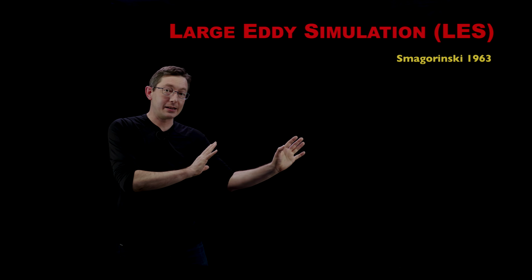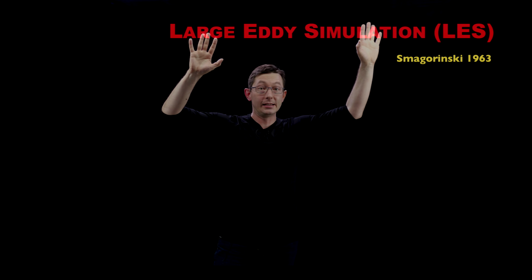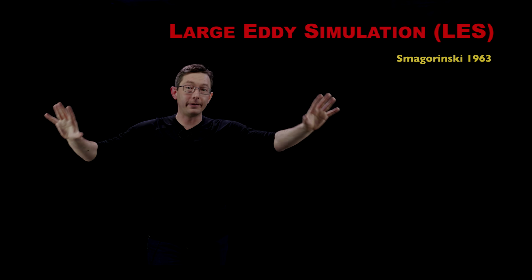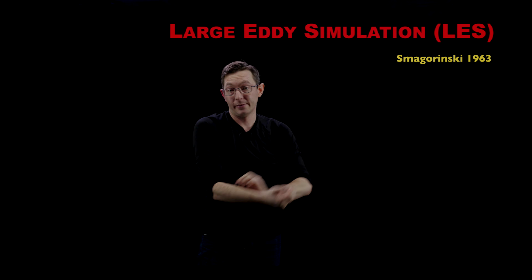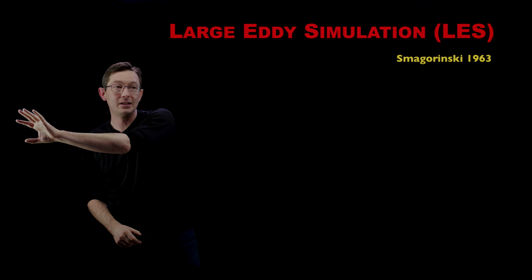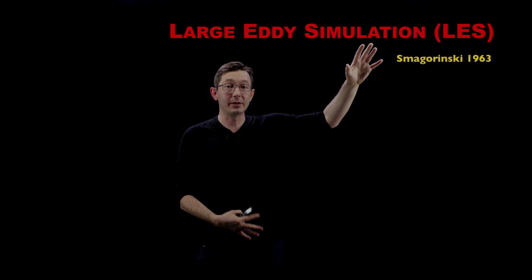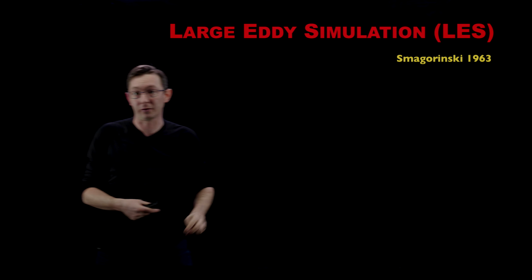Now for the rest of this, I'm going to tell you about a whole different perspective called large eddy simulation, or LES. These are really the two big families of turbulence closure modeling: Reynolds averaged Navier Stokes and large eddy simulation. LES was proposed more recently. Remember Boussinesq was 1877. Large eddy simulation was proposed much more recently, in the computational era, by Smagorinsky in 1963.